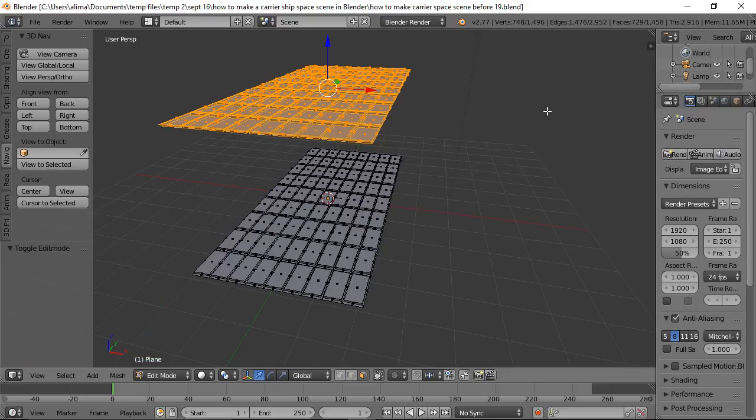Sometimes when you're working in Blender, you'll notice that the shading looks kind of strange. A lot of times when that shading is strange looking, it's because your normals aren't facing the right direction. Again, normal basically means which direction a face is facing. So imagine you have a piece of paper, right? Typically a piece of paper has two white sides, right? So imagine the part of the paper that you put a drawing on. That's the side you want to show, not the back part. You want to show your drawing. So that would be, in a sense, kind of how your normals are facing.